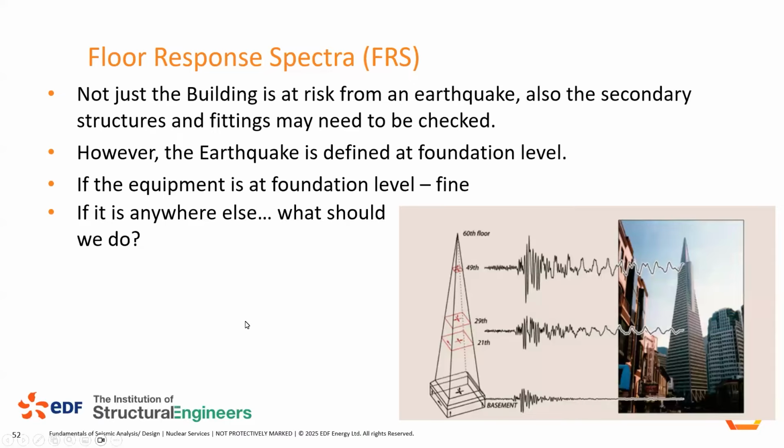And then my last one, and just slightly over time, but we'll finish hopefully at 10:20, floor response spectra. I think everyone should be aware of this too. So we define an input motion. The input motion is defined at foundation level at the base, and it can be used for anything that sits on that base. It can be used for the design of a building because it's connected down to that foundation. It can be used for the design of equipment that sits at that foundation level.